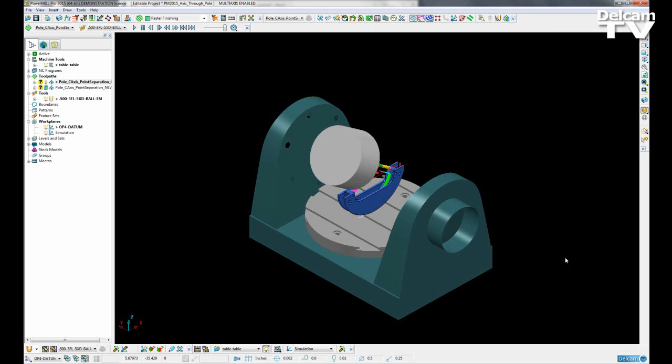In PowerMILL, when machining a continuous 5-axis toolpath, sometimes we encounter problems when the tool axis passes close to the machine tool pole, which is typically the vertical axis, or Z, where the A or B axis is controlling the elevation and the C axis controlling the azimuth angle. As we approach the pole, the tool axis may have to go through a very rapid change between points as it passes through or close to the pole.